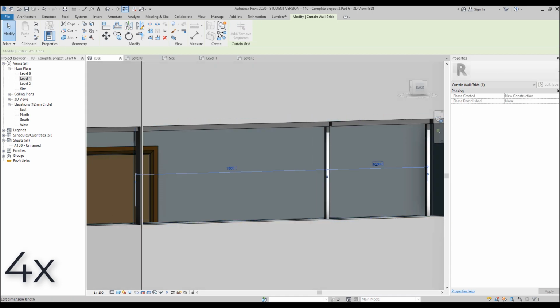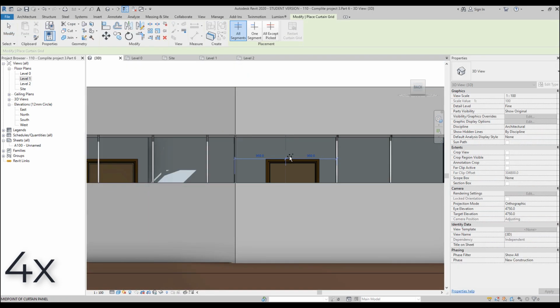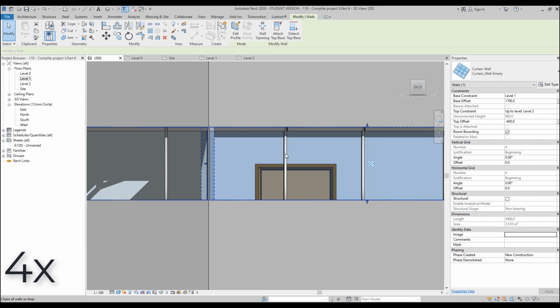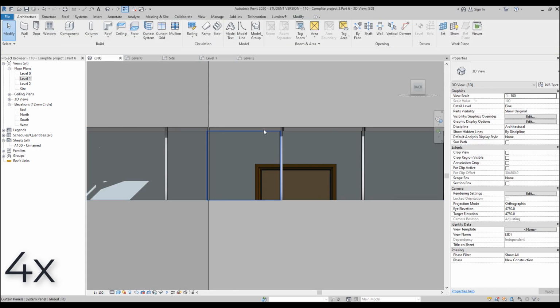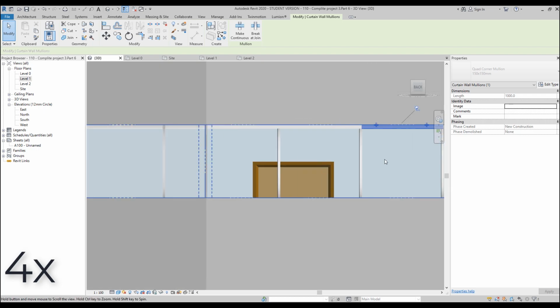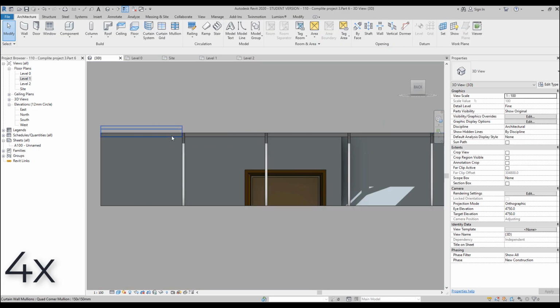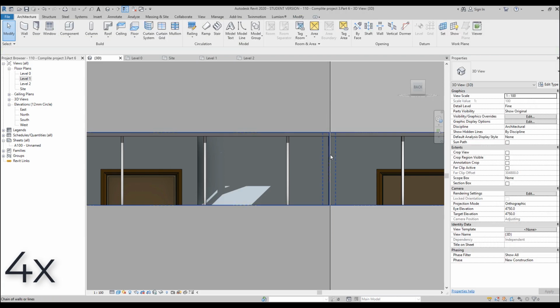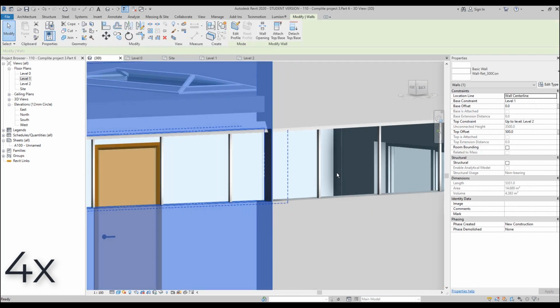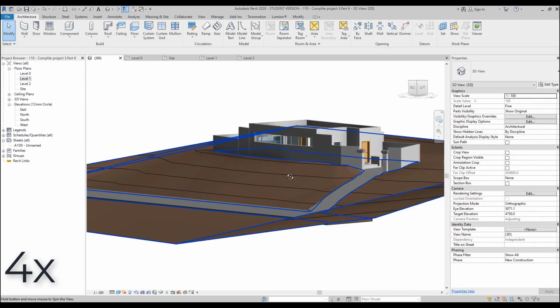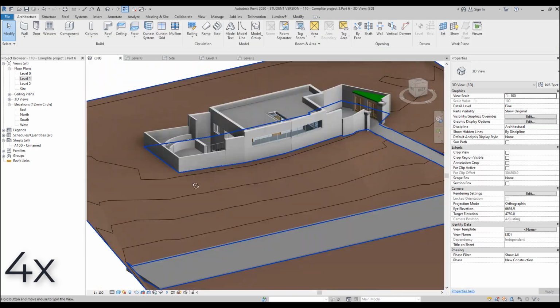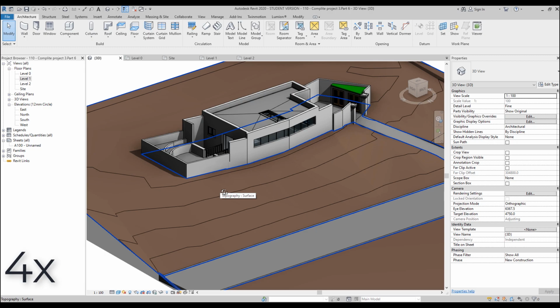And don't forget about the connections of the mullions too, because my connection now, as you can see, is cutting the main mullion, and I'm just changing the position of the mullions one by one. As you can see, I'm connecting them with each other, and we get a result like this. Now I'm connecting my middle part, and we get a pretty nice result to continue.